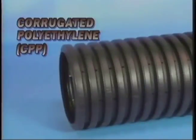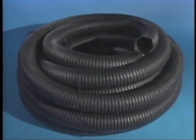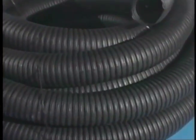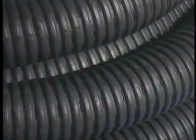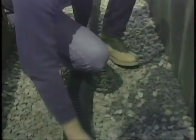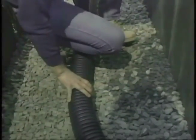Corrugated polyethylene pipe is primarily used in and around buildings and highways. Common joint lengths for this pipe can range from 20-foot lengths to rolls of 100 feet or longer. Since the perforations are randomly located around the pipe, there are no specific installation procedures regarding the perforations. CPP is a flexible pipe and requires considerable attention during installation and backfilling procedures.